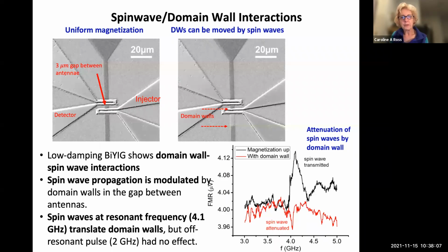And the spin wave, or magnon, occurs at about 4 gigahertz in this particular material. And at that resonant frequency, there's a good coupling between the signal in the antenna and the spin wave generation in the garnet, and that allows for an efficient transfer of energy, or a more efficient, I should say. If we run off resonance, then we don't see any of these effects taking place. So this gives us another avenue to explore in terms of electrical excitation of magnetism in these kinds of materials.